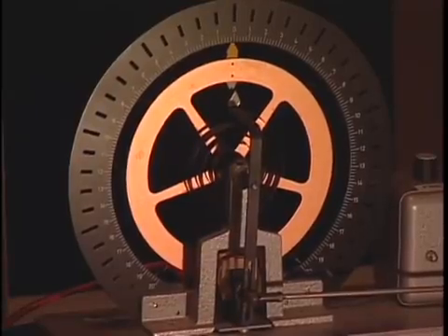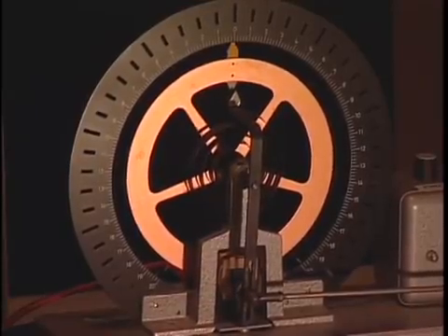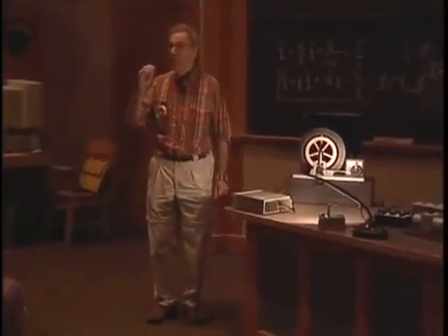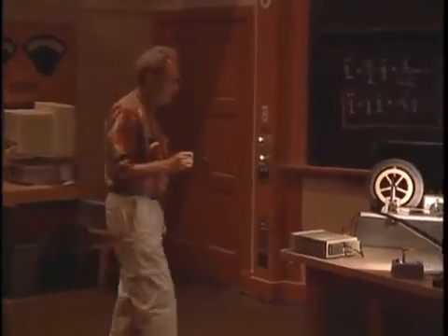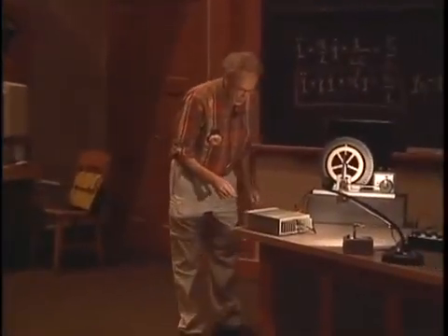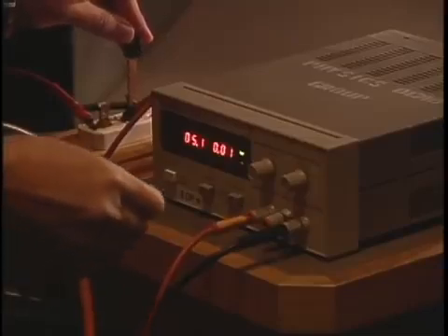And the reason why I can say with confidence that it's still underdamped: I release it at 0 speed. And if I release it at 0 speed, and if it is overdamped, it can never overshoot. And yet you will see that there is a minute overshoot. So it is still underdamped, but it's getting very close to being critically damped.